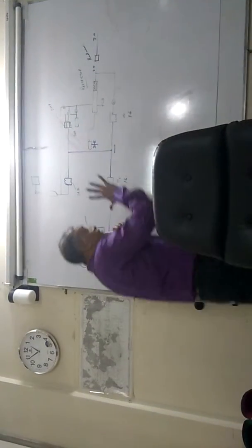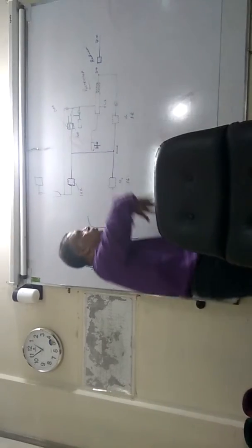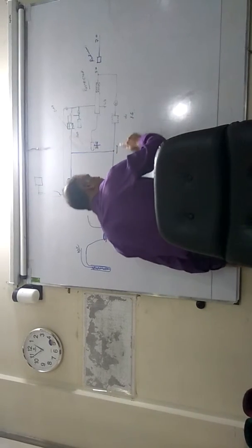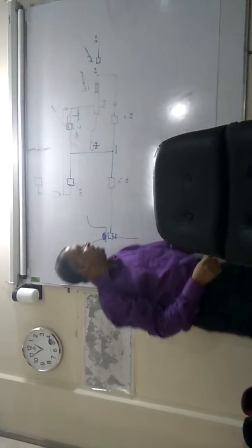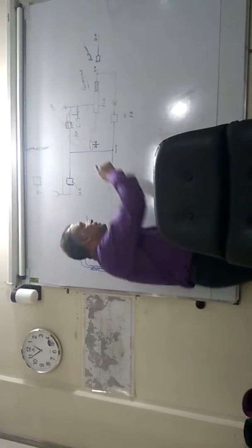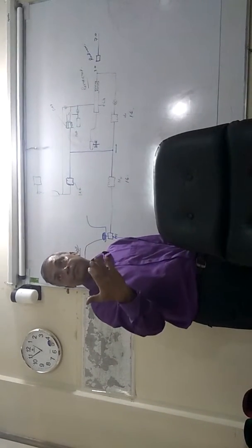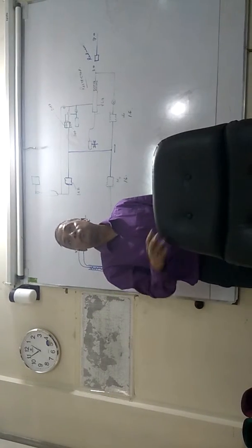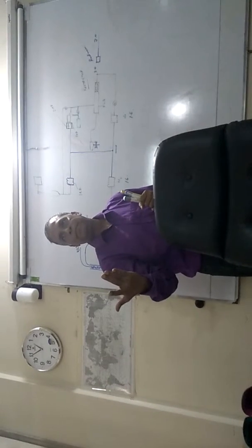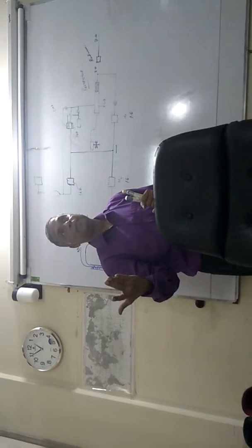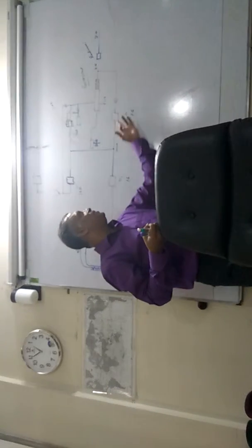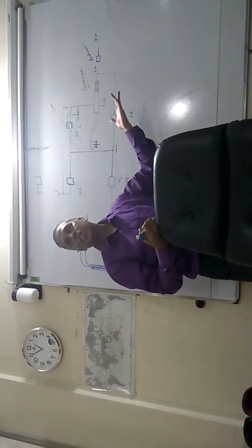Now, imagine nothing is happening in the rest of the places, that is, everything stays where it is. Now this movement to the right, what happens? The distance between the nozzle and flapper is reduced. That means the air that was coming out earlier now cannot come out completely. So that will mean this pressure will show an increase. Agreed? So this thing that we got, this is the difference between these two, which is causing it.